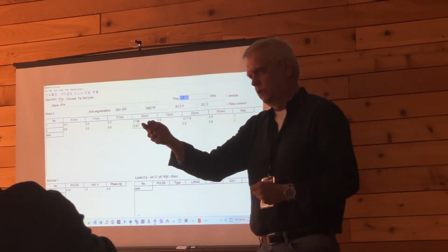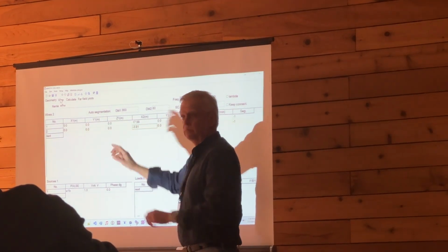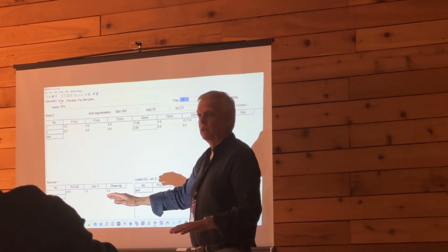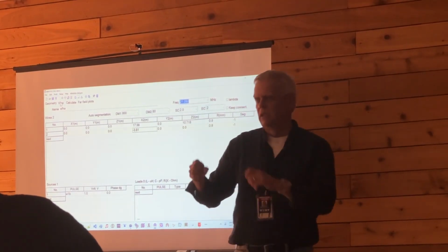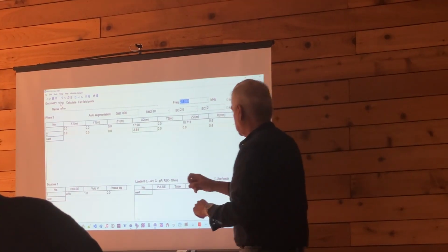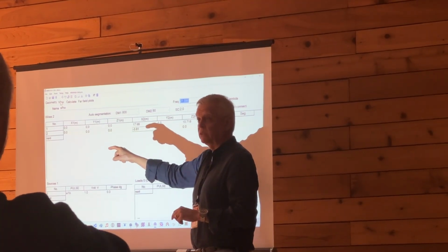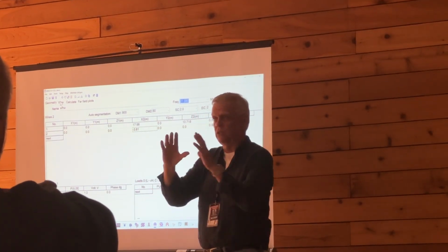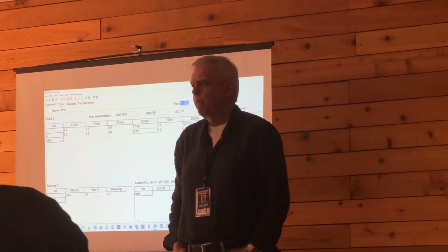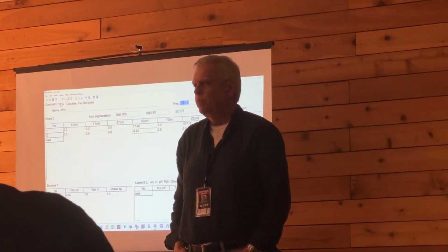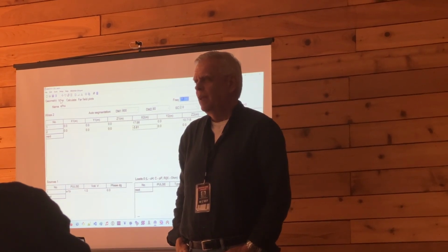Going back to your comment, yeah, the first optimization gave us 3.81. We left it frozen. We didn't mess with it. But if you think about it, we told the optimization panel to consider this element right here. It changed this one for sure, but we told it, hey, you're free to change this one also. Before you leave the gauge, I was just going to ask you, why didn't you change the long wire first? I know it's easier to change the counterpoise, but what would happen if you changed that one?